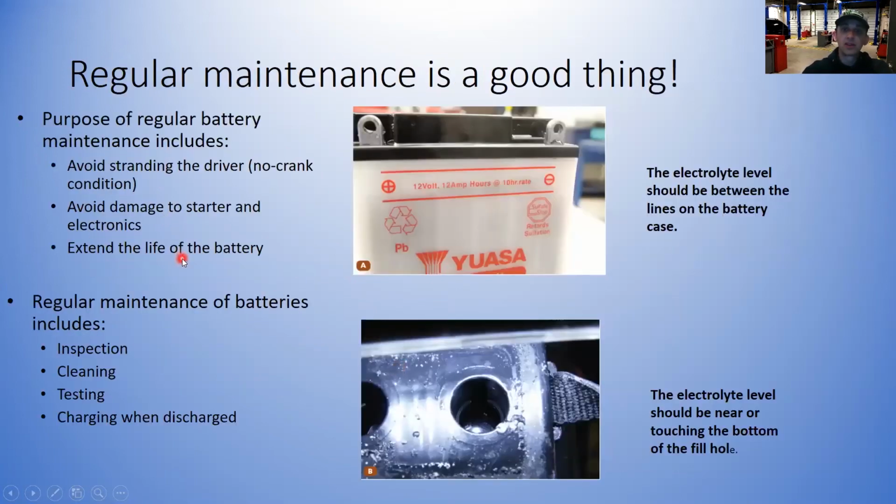So remember, regular maintenance is a good thing in the vehicle overall, but especially with the battery, because the purpose of regular maintenance of the battery includes leaving you stranded somewhere. That's what you're trying to avoid, is leaving you stranded somewhere or the customer stranded somewhere. Nobody likes to come out from dinner and turn the car on and it doesn't crank over. Also avoiding damage to the starter and electronics, because a weak battery can cause damage to that stuff, and just overall extend the life of the battery.